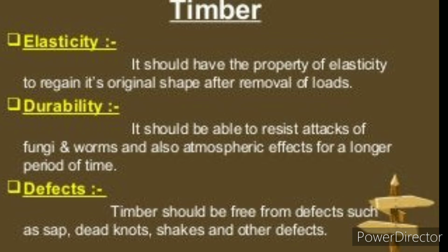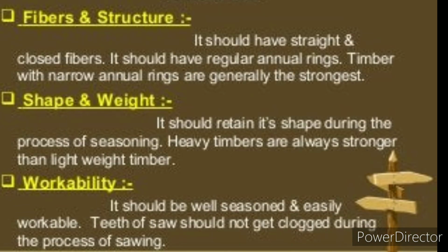3. Durability. A good timber should be durable. It should be capable of resisting the actions of fungi, insects, chemicals, physical agencies, as well as mechanical agencies. 4. Elasticity. A good timber should retain its original shape even when the load causing its deformation is removed. 5. Fibers. The timber should have straight fibers. And 6. Fire resistance. The timber should be a bad conductor of heat. A dense wood offers good resistance to fire.